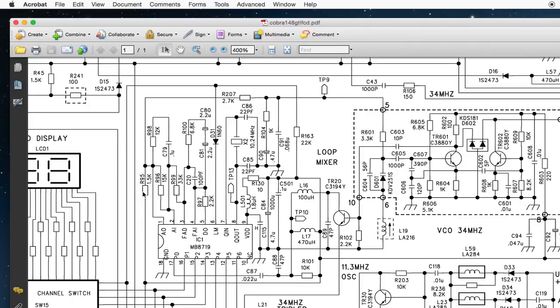That is a pull-up resistor just here. Now, what that is doing is biasing the pulses, so it will pull it up a bit, and it may actually, in some cases, cause problems if the phase detector is not being skewed in one direction or the other. If it's too neutral, it may actually go out of sync with the incoming frequency and have trouble locking. It will go so far out of phase it can't do it. So having a pull up or pull down resistor, depending on the radio, helps to pull the phase detector in one direction to make it bias, as it were, in one direction, which helps it to get lock.